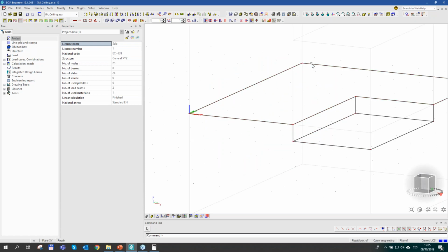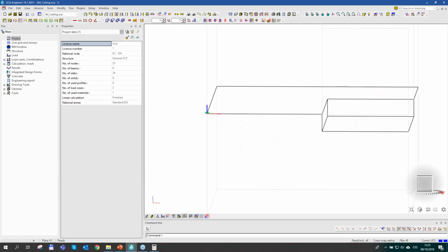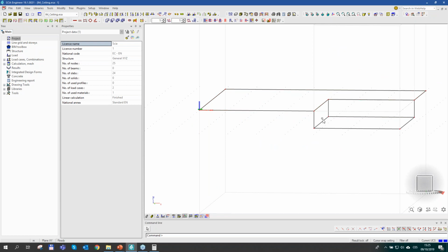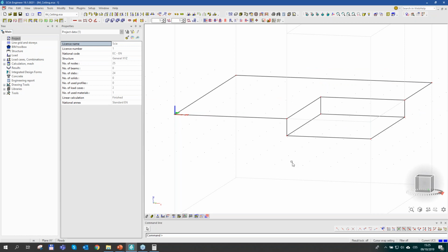And I have a ceiling here that actually has 2 levels. So there's actually a bit of a level change in here. Not enough to have a separate ceiling, just enough to make my calculation nightmare. Because how should I define this? It is sort of a rib. However, our current ribs will not support this use case because one slab is added at the top, the other one at the bottom. But I can use integration member for it. So let's have a look.